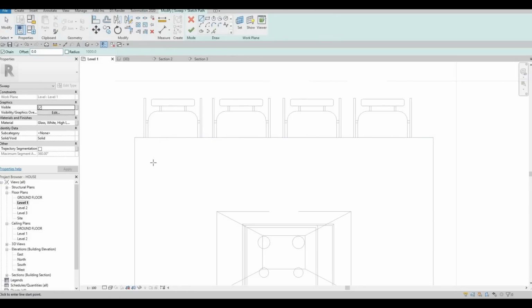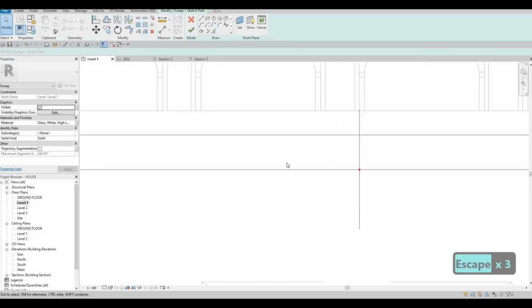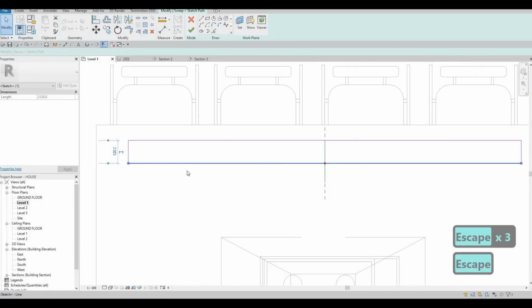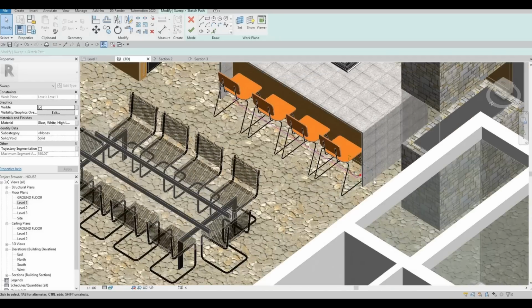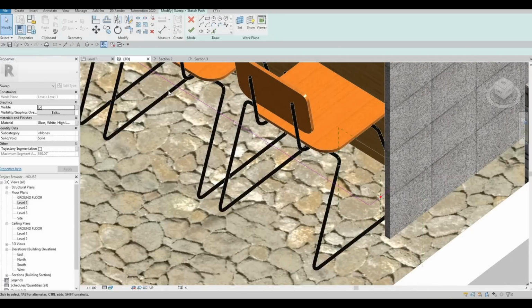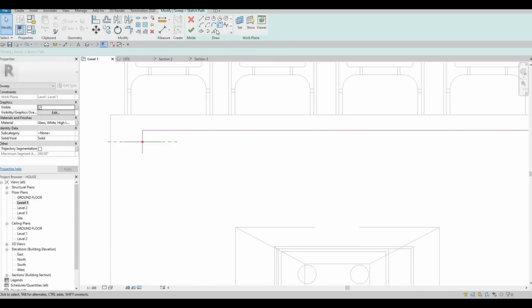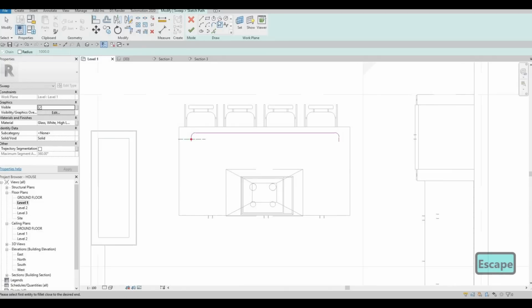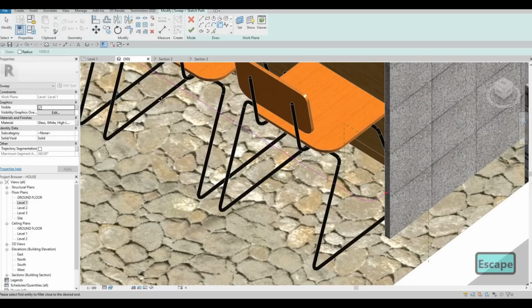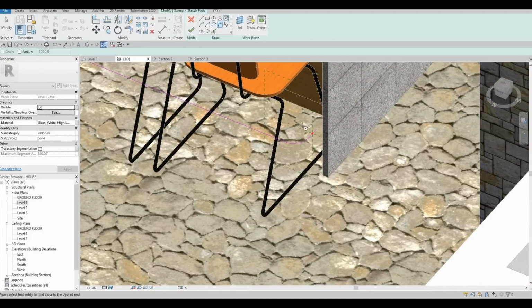Sketch a path. I'm gonna sketch this one right here. Make it rectangle first. Somewhere right here is the location. I'm gonna delete this one, and let's go onto this part right here. I'm gonna curve it. So to curve it, I'm going to use fillet arc, and then maybe 60, and then 60 here as well. So that now that it's curved, we could go to 3D and then create our circle right here.